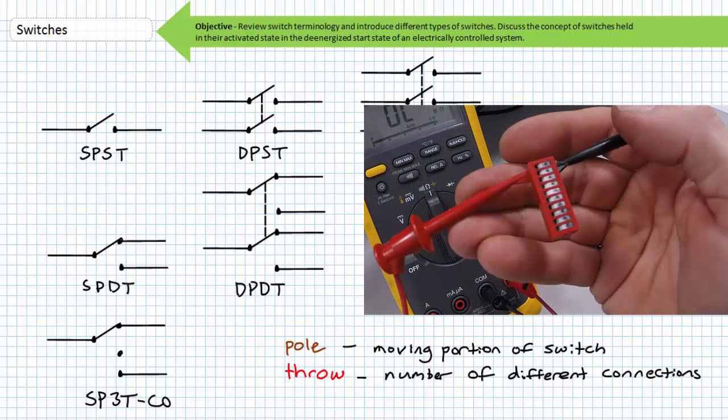A number of independent SPST switches can be housed in the same package, where each one is electrically isolated from and is capable of being closed and opened independently of the others. Each switch is therefore an independent and isolated entity in no way, shape, or form connected to any other switch. The package would exactly be that, a package. It just holds a collection of switches together. Don't confuse the package with an individual switch.